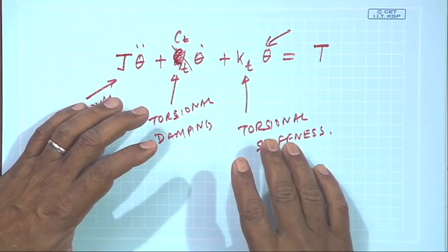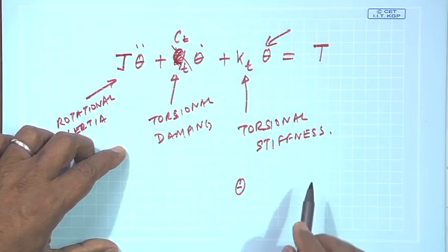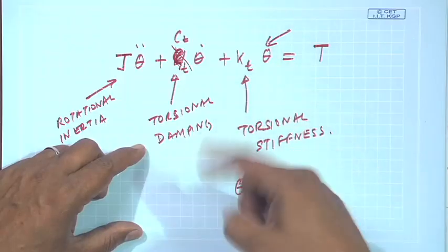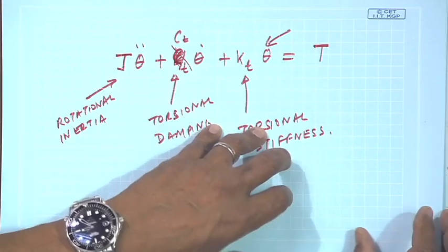The theory which we understand in linear vibrations also holds true, and like we had linear dampers, we will have torsional dampers. Particularly, we will see in many of the ships, or many systems where there is a large propeller shaft rotating, to reduce the oscillations in the theta domain, people have put torsional dampers in the system.